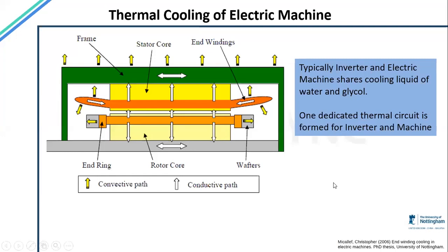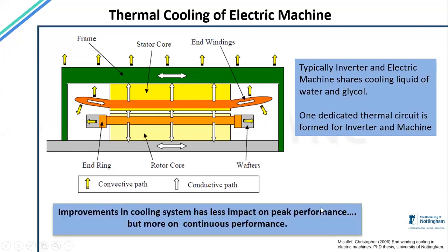The end winding cooling is very important because the end windings are all in air, so we have a very high thermal resistance in this area. So how to cool these? Whether we should have some dripping over here, or some shaft cooling, as we call it. These are all different studies that we have to do: thermal resistances, conductivities, and those governing equations.